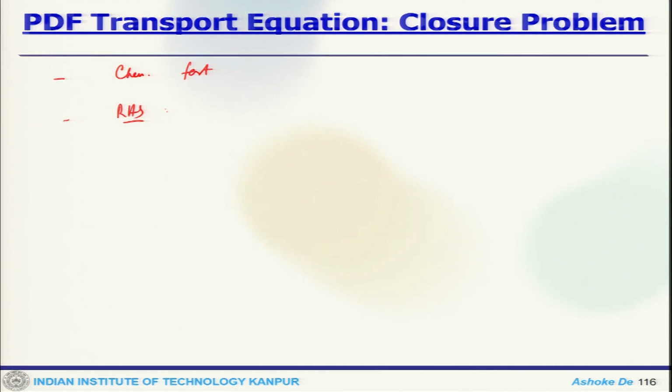This was illustrated by Pope in 1984 for premixed combustion, comparing a standard PDF closure for molecular mixing with a modified formulation. The molecular diffusion term was combined with the chemical source term to define a modified reaction rate. Distributed combustion and flamelet combustion show considerable differences in Damkohler number dependencies.